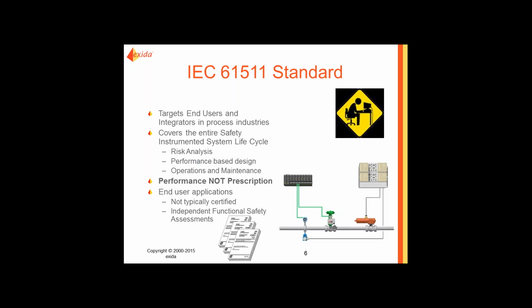And from an end user perspective, end users are not typically certified, but the standard says that there should be at least 5 functional safety assessments performed throughout the life cycle. The only one that's mandatory is what we call Functional Safety Assessment 3, FSA 3, which effectively is the pre-startup functional safety check, where you make sure you validate to ensure that you've covered everything and that the SIS meets the SRS in all its entirety. So this is often known as the pre-startup safety check.